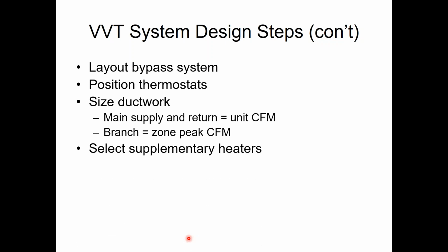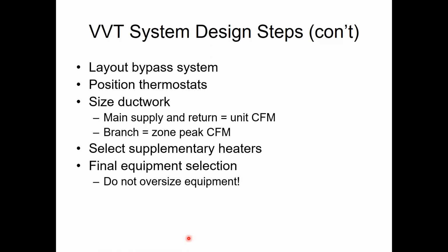I may need to select some supplementary heaters, specifically if I decided to mix exposures or mix some interior and exterior. I'm going to have supplemental heat. I can do VVT jobs with no supplemental heat, but it requires me to be smarter about my zone layout. And then I'll go back and tweak my equipment selection from the earlier preliminary selection. It's very important not to oversize the equipment. All of you have been in enough of my classes and webinars to know that I hate oversized equipment in general.